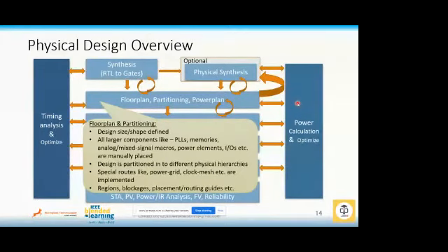Let's say you have RTL code you have synthesized for the first time. You look at it. Let's say you have ended up with a million transistors, million gates. So based on that, you define the size and shape of the floor plan, and then you start floor planning a design. So all the larger components like PLLs, memories, analog mixed signal, macros, all of these are placed in a floor plan, and your power elements, IOs, all this has to be put in a way that I'll explain with an analogy so that you will get a better picture of how we do floor planning.